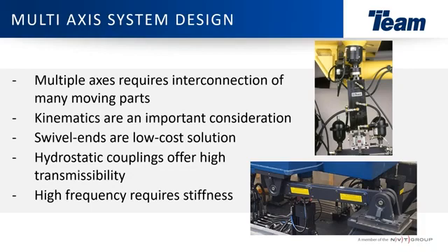One of the typical test setups for 6-degree of freedom systems is a 3-2-1, where you have 3 actuators in the vertical orientation, 2 in one of the horizontal directions, and a single actuator in the second horizontal direction.